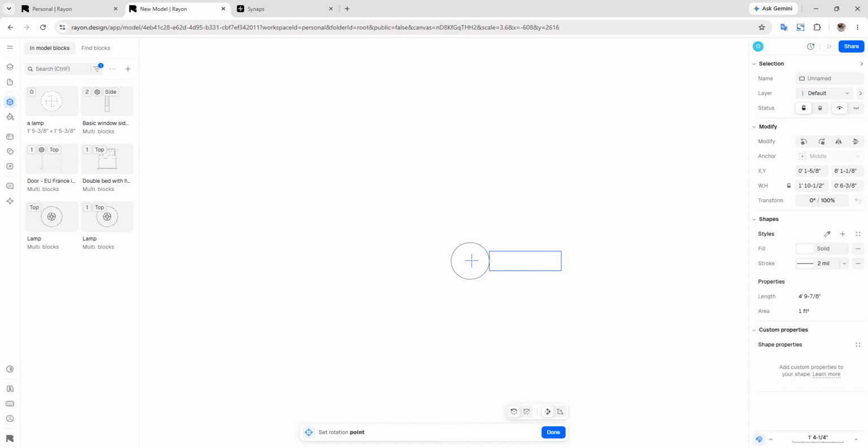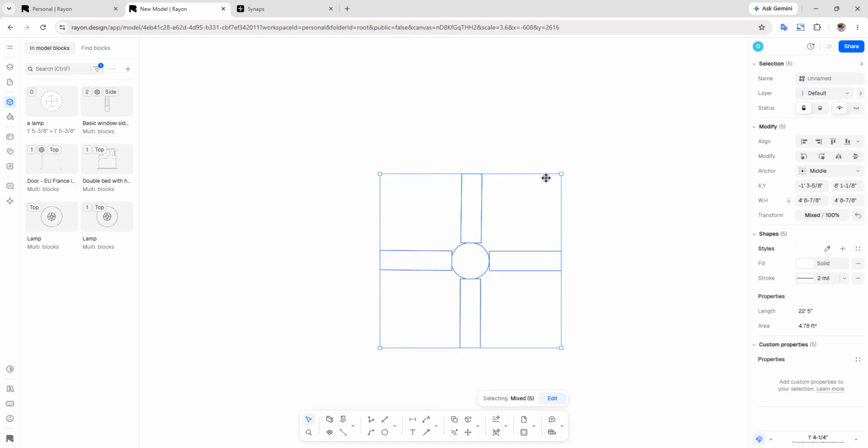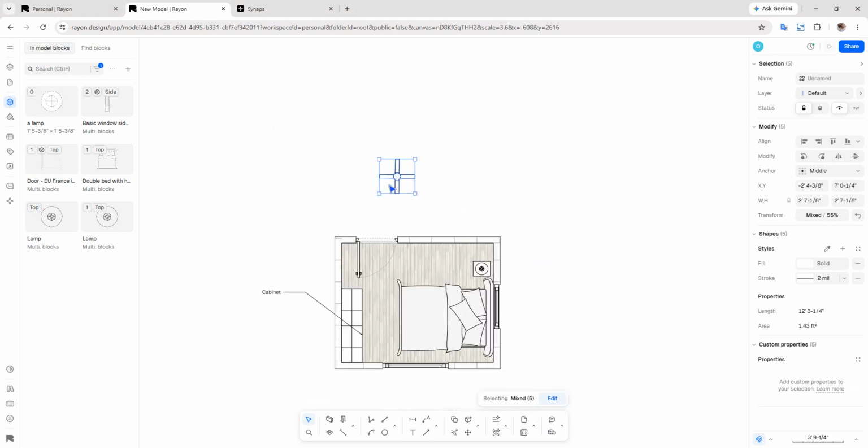Okay, so click here and make the angle appear 120, enter, and it's asking for distance, right? Why are they asking for distance? Okay, anyway, make the count 3. Done. Okay. This is what is happening right now. Usually I don't work like that. Usually I don't use polar array mostly.